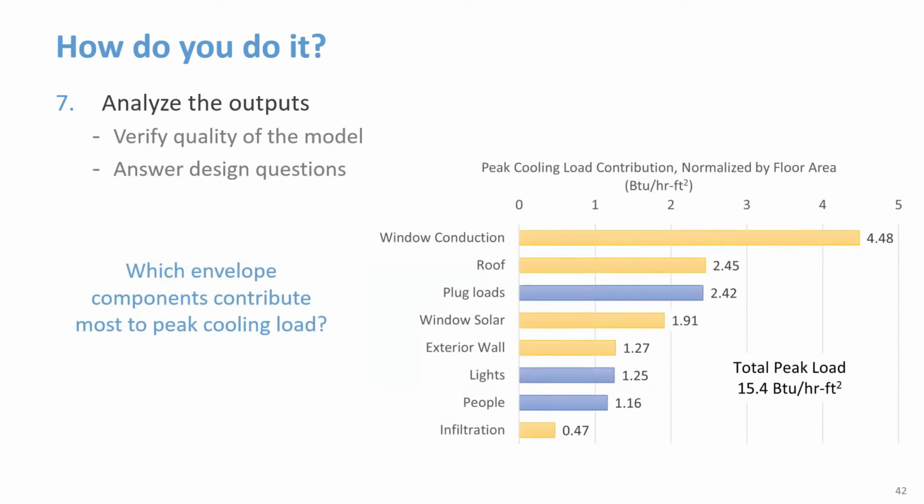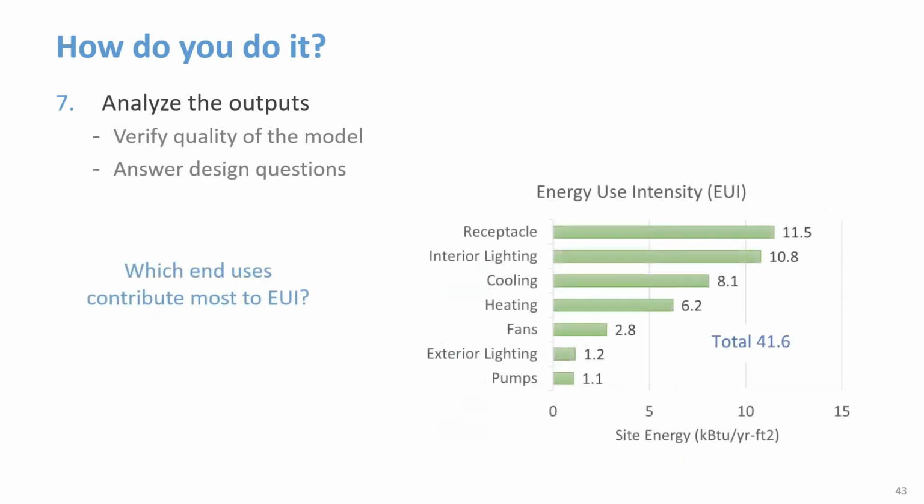The analysis might look at detailed output from a single model to answer a question like, which envelope components contribute the most to peak cooling loads? That'll help you focus effort on design to reduce those loads. Or another question is, which end uses contribute the most to energy use intensity? Also a useful question to help you focus your design efforts.